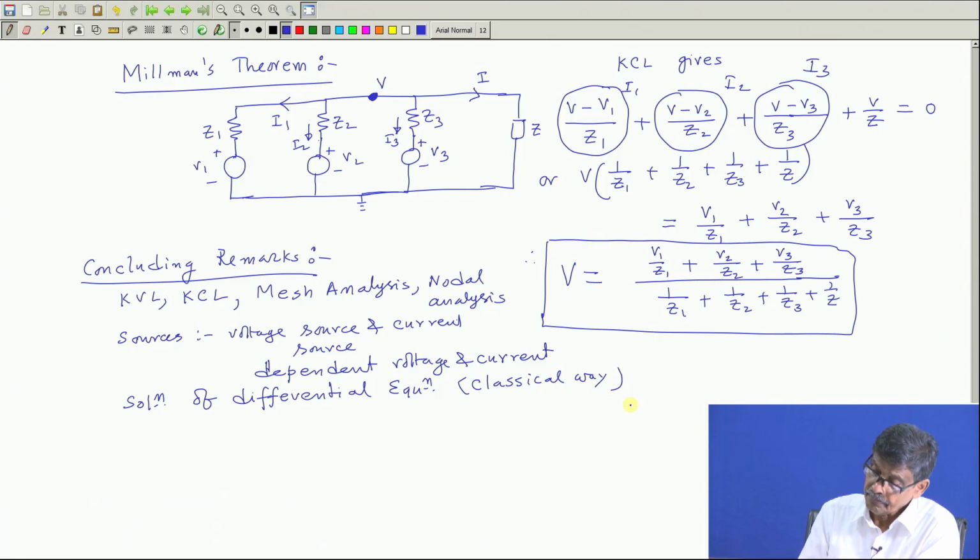Okay. After you have done this, it also gives you both time domain as well as steady state response. The usual order of any circuit time constant is some milliseconds, or in terms of supply, 20 millisecond period for a 50 hertz supply, there may be 2-3 cycles of supply. After that only steady state prevails. Then we introduced the phasor notations, how to get the steady state solution straight away. That is also an important thing to know. Okay. So, solution of differential equation.